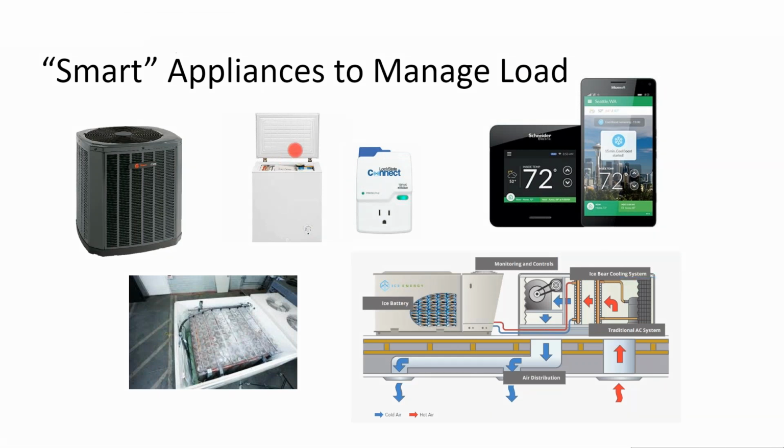So for that heavy-duty deep freeze, instead of putting it on a timer, you have it turn on whenever you're outflowing onto the grid or whenever your battery is at a healthy state of charge, and have it freeze food with your surplus electricity and then coast at night instead of drawing load off your battery bank.